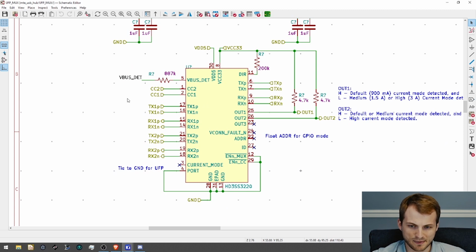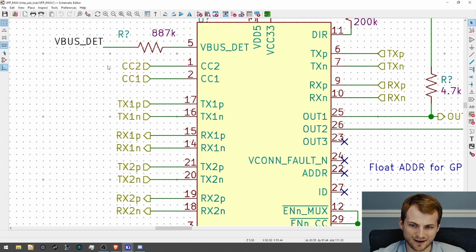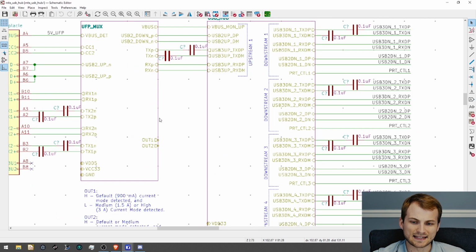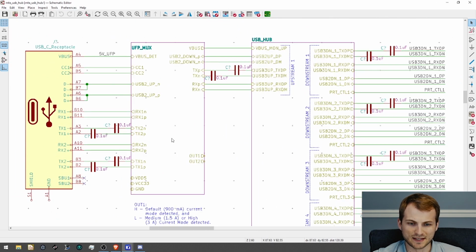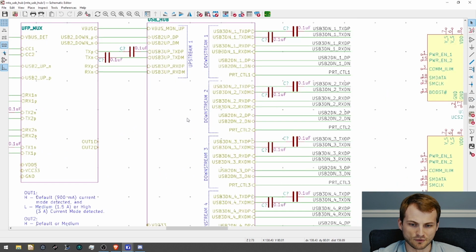But for every pin, and this is something I try to be very cognizant of, when you are outputting a hierarchical label, I make sure to always do it with the exact name of the pin it represents. It's not overly important for this design, but when I'm doing projects for work, I'm not the one doing the programming.